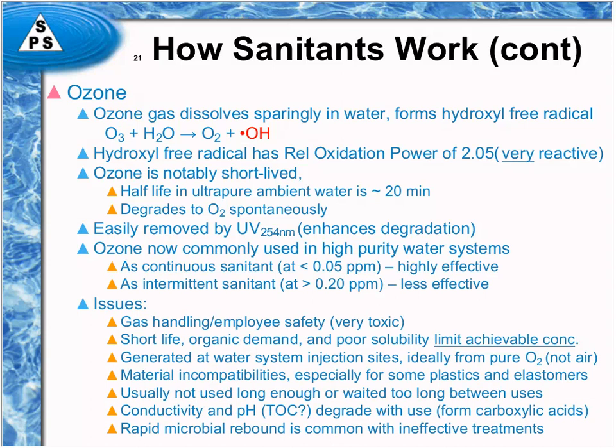It does have gas handling issues, and it can actually degrade the chemical purity of water by releasing TOC into the water, because of the organic matter that's degraded to form carboxylic acids, which are conductive, and so they degrade the conductivity of the water. And also degrade the pH of the water and make it become more acidic. So usually you have to have some sort of polishing treatments in order to keep the water purity if you're using ozone continuously.